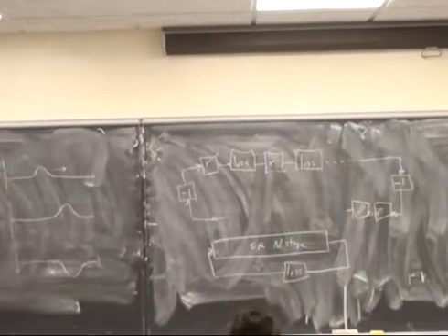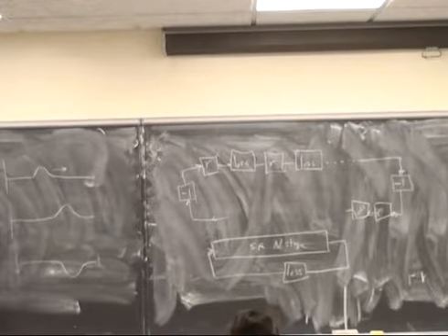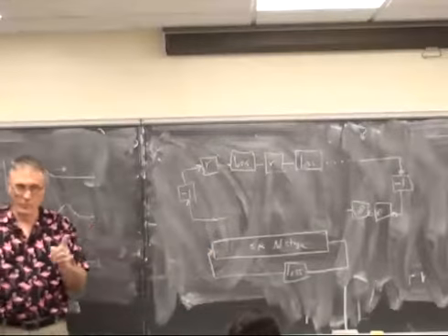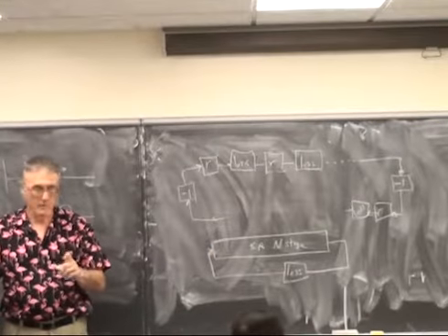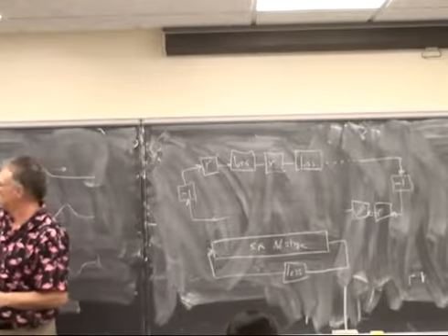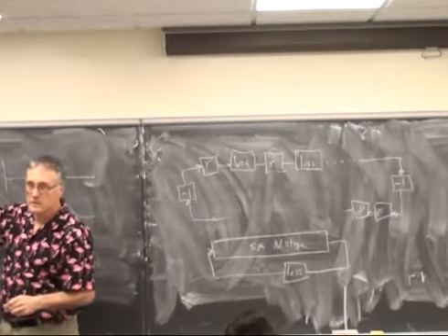So for the cost of one multiplication per time step and a movement of a pointer, really you don't have to shift everything, you just move the pointer if this is a circular buffer, you can simulate a string, a one-dimensional linear system.